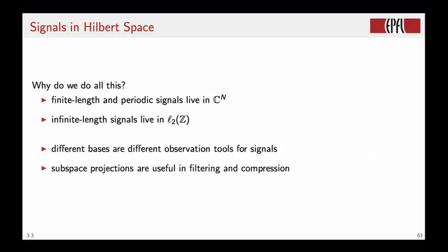And when we do subspace projections, we will see that we can do filtering, which will be explained, of course, in detail in this class, and we can do, for example, image compression. So the notions we have seen, one was to build bases. That's important. These are like our tools to look at signals. And another one was subspace projection, which will come up a lot when we do approximation and in particular when we do compression. Let me just finish this properly here. We have an origin, we have a subspace S, we have X, and we have an orthogonal projection, and we have the orthogonality principle.